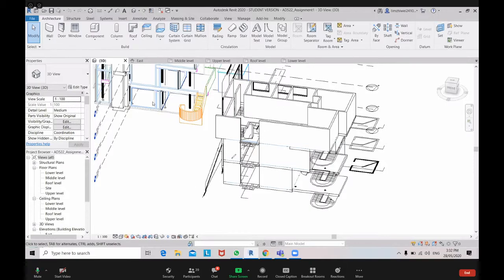Okay, as you can see, the north is still this one, the default. So basically, in order to change the north, you have to select the project base point. You select it here, this point. Zoom. Okay, now you see we have here angle to true north.